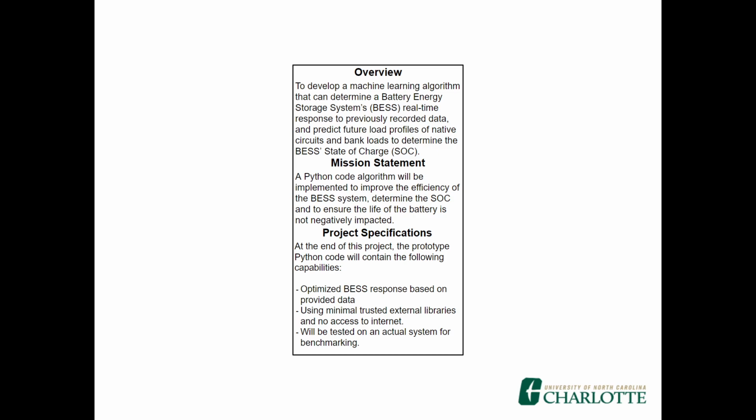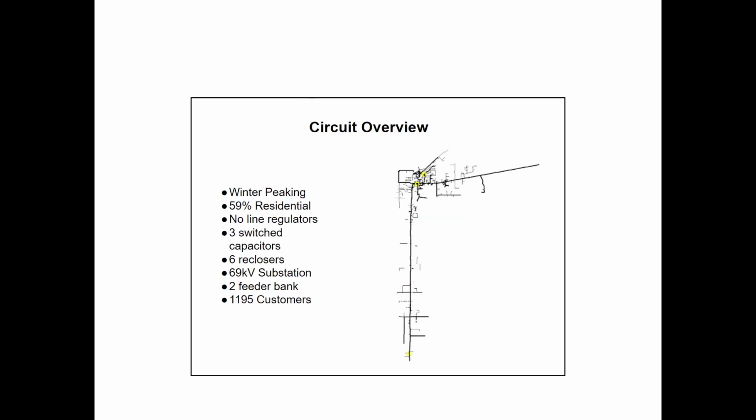Our team's mission statement is shown, also our project specifications. The feeder is one of 2 feeders in a bank. The circuit appears to be winter peaking and 59% residential. As for critical components, the feeder has 3 switch capacitors, 6 reclosers, and no line regulators.